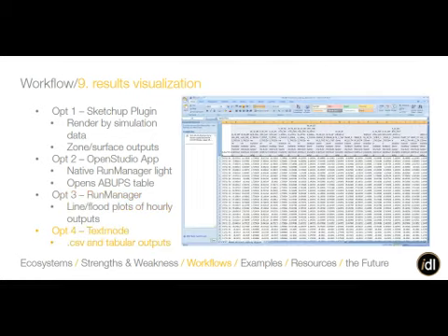Last but not least, there's text mode. It spits out all these output files. There's a CSV that contains all of your hourly output information over your time step. Sometimes you'll have 400 columns of all the zonal analysis, 8,760 rows if you do a 1 hour time step. Sometimes we do 6, and these files get to be like 3 gigs of text, right? So they can get crazy. But they're the most flexible, right? So we'll do a lot of custom post-processing with Excel right out of these CSV files.